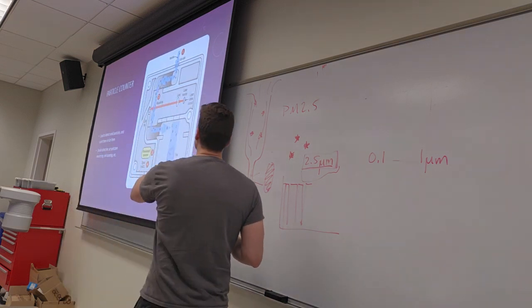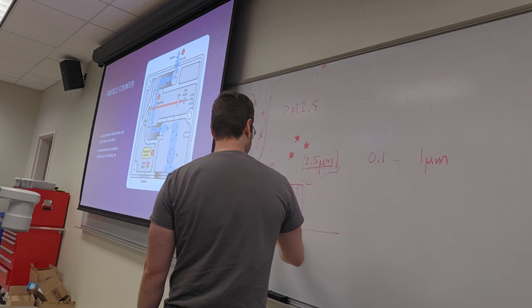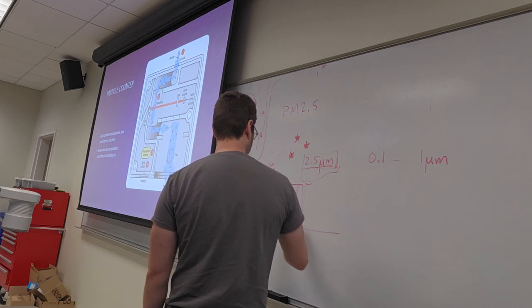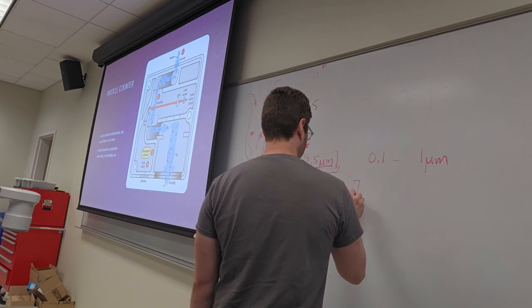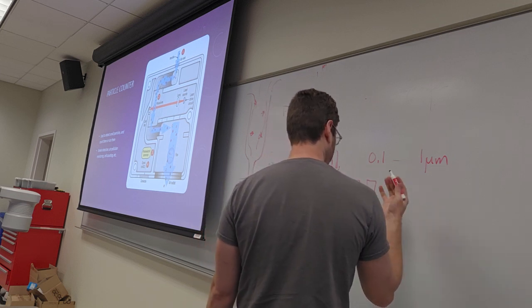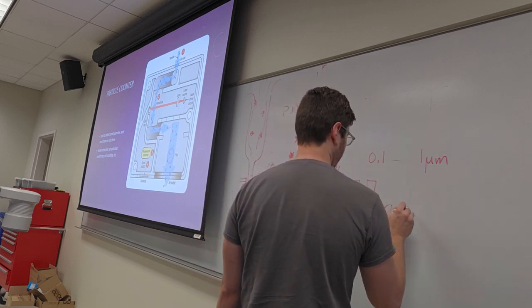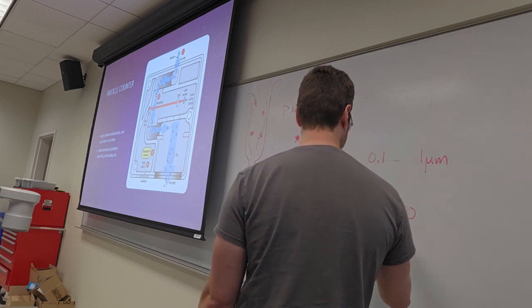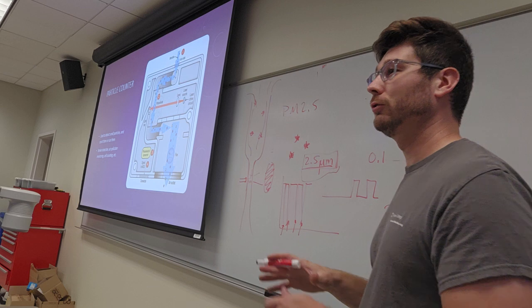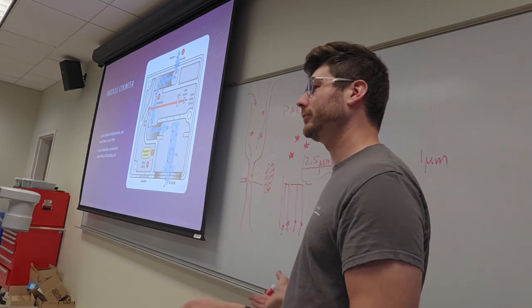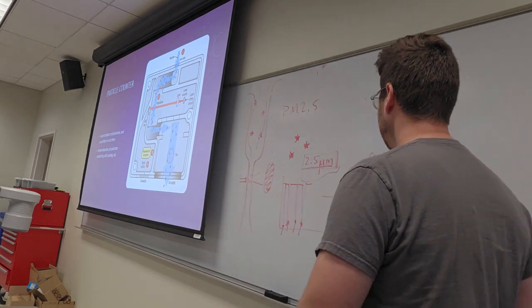There's a computer inside of here that counts these pulses, or has its own algorithm that can turn these pulses into a simple UART data line that says some number. Typically that would be like 250 or 50 or whatever particles per second, say. And then you map that to air quality and health hazards and all that stuff.